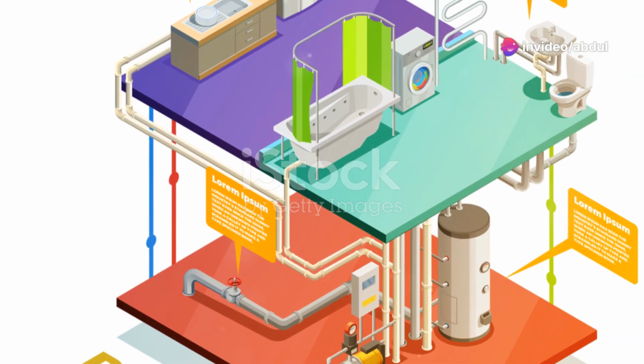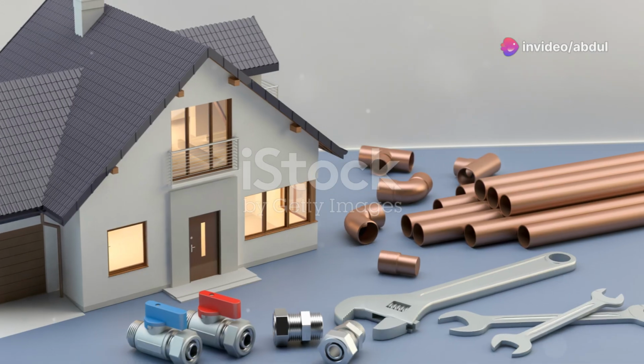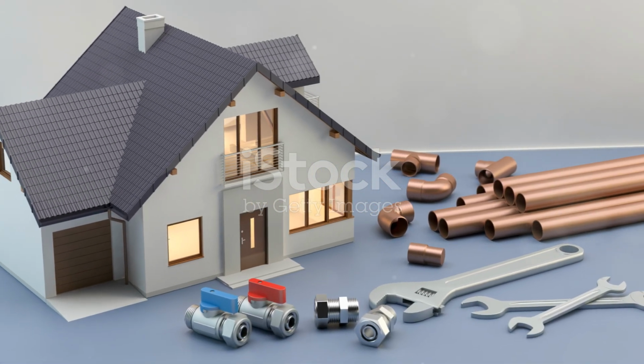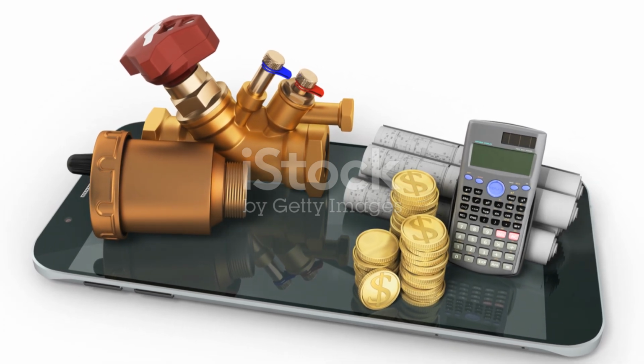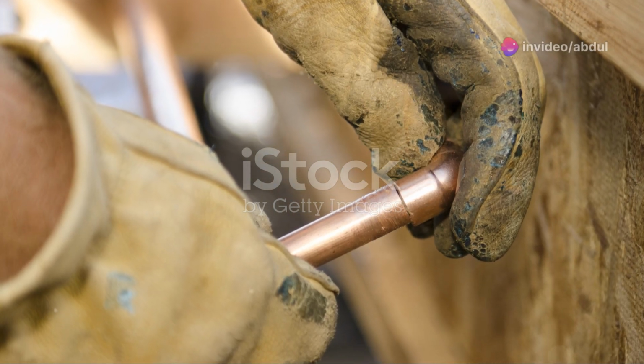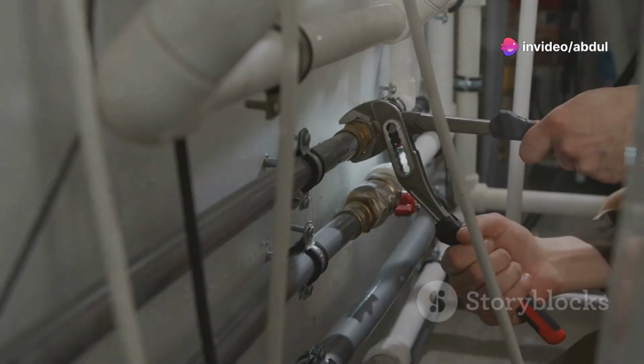Once you have a collection of blocks, you can save them as a drawing file and then import them into any new drawing. This way, you'll have your own custom plumbing symbol library ready to go. Next up, we'll learn how to place these symbols on your base plan.